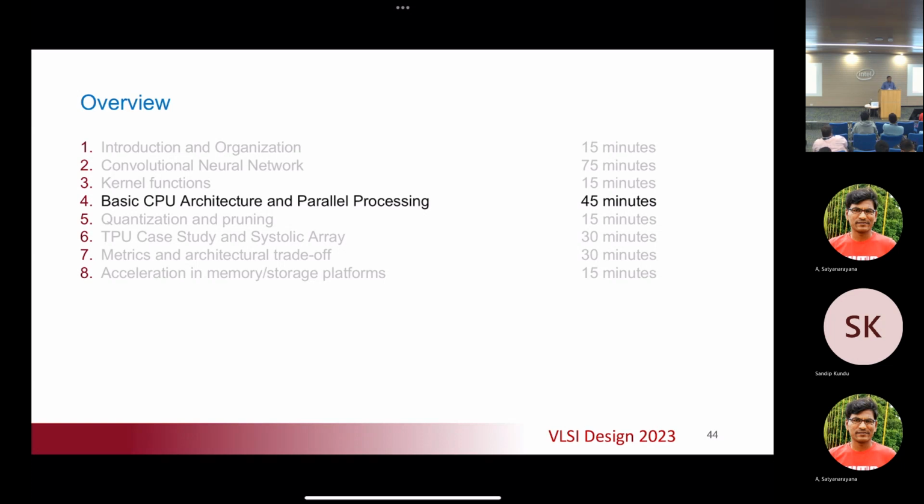This has a tremendous implication on the decisions that people make in hardware design. For example, the tensor multiplication unit that Intel has put in Sapphire Rapids has 16 rows and 64 columns. That would work well when the filter size is less than 16 when you multiply that, so that's like a 4 by 4 filter. But if you do a 5 by 5 filter, then during the convolution process you have to tile that operation, you have to rewrite the loop slightly differently.